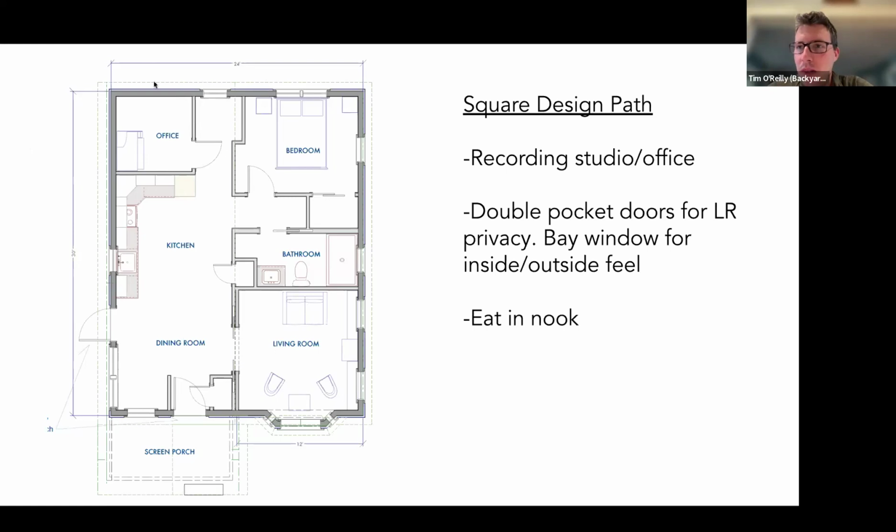So one of the two folks moving in does sound recording, and he needed an office and a space he could close off and soundproof. So we designed within their footprint this small office with its own door. We also added some sound channel clipping and some insulation to make this room really quiet. You'll see along this marriage wall here, there's a lot of different gaps. And so they designed in nooks for storage. So in that hallway bedroom, they've done these offsets in the wall where they can add furniture storage now.